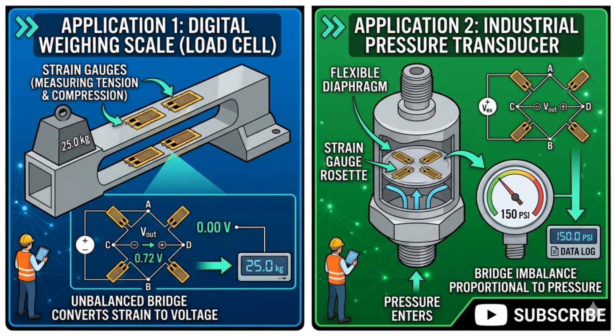Another example, they say, is most weighing machines. This is the whole idea. Within the circuitry of that weighing machine, especially for those measuring very small, minute weights like micrograms and milligrams, you have these strain gauge devices connected to a balanced Wheatstone bridge.